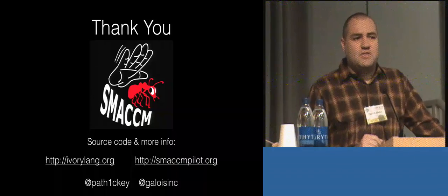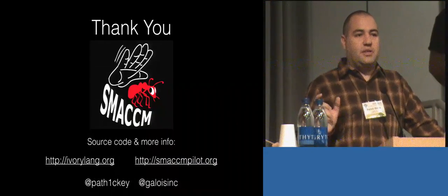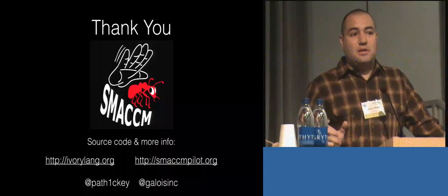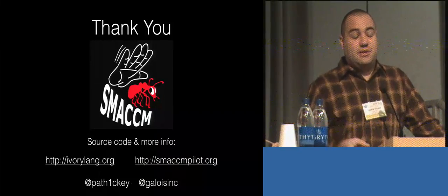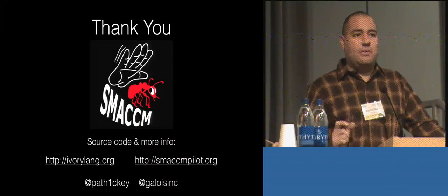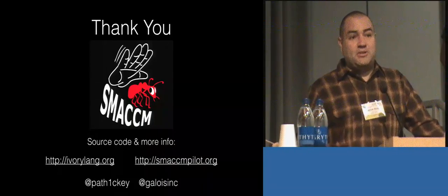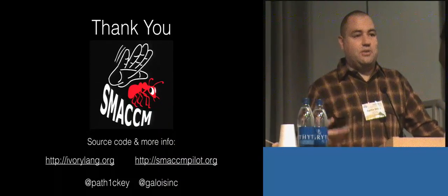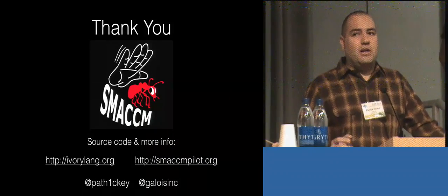So we do have a way to collect the amount of global memory that you use in a program. That's just a basic C compilation; the linker can tell you. We don't yet have a way to analyze the maximum stack depth that you use. We do have, down in the operating system level, a way that, once you've exceeded your stack, it halts in a certain way so that you can attach a debugger and find out some information.